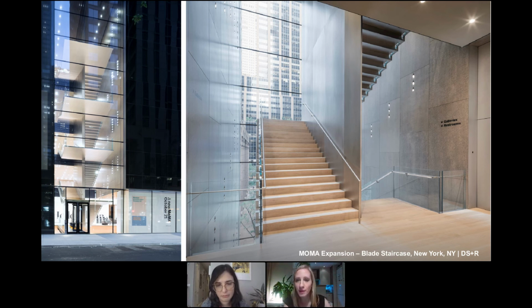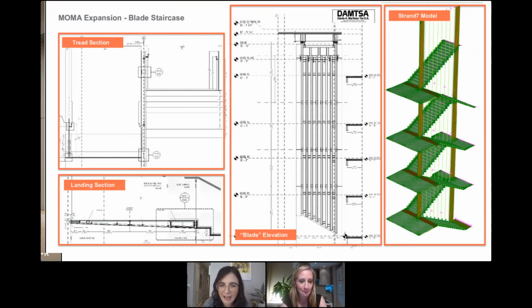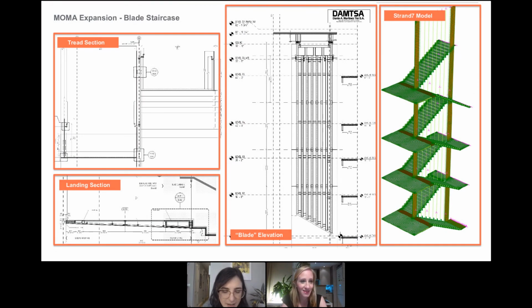Okay. And what kind of supports were considered at the full landings to the main slab? I think you've probably just sort of answered that one. I don't actually have the landing details in here, but they're mostly just pins, but they are providing some restraint. Yeah. And restraint laterally as well in both directions.